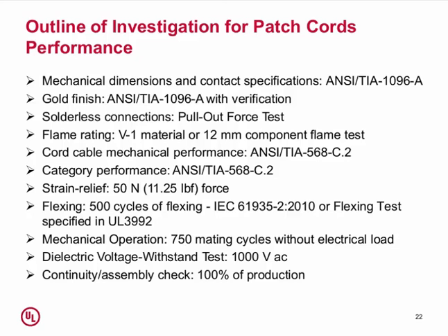For category performance, same thing. So the requirement for patch cords found in TIA 568-C2 is applied. That's part of the checking process. Make sure the cable meets and continues to meet 5E, 6, 6A from that standard. There's a strain relief test. It's about 11 pounds or 50 Newton force. That's applied to the cable to see if we can pull it out from the plug.